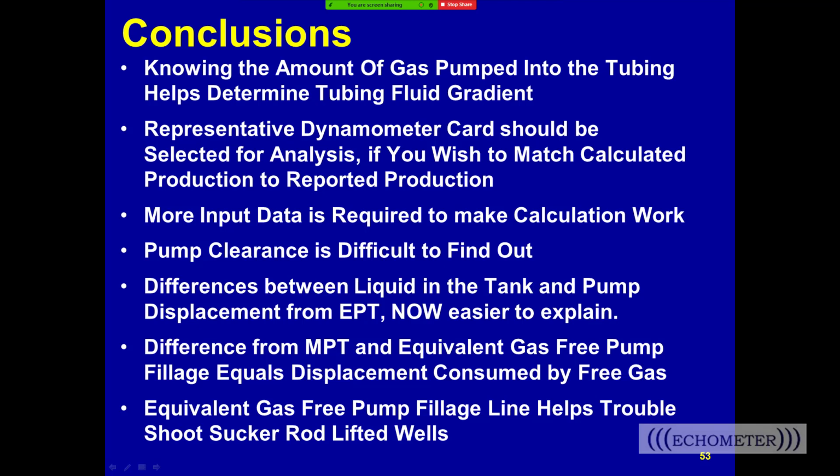Most of the wells that we see in this area are typically not that shallow. They're deeper than 3,000 feet, and we usually don't see the wavy character on our pump cards in this area. We usually just see one hump. It's not wavy.